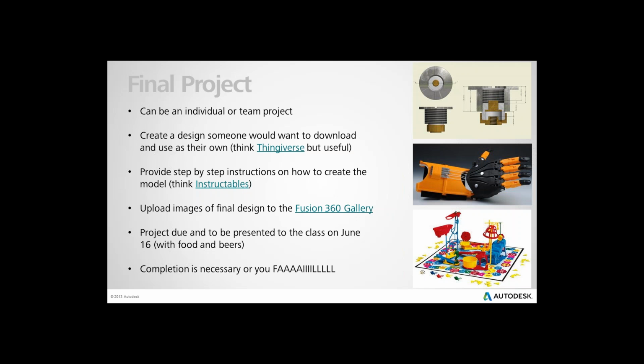You don't scale stuff. Parametric is exactly that. This is a parameter to the function. It will behave exactly in the way you describe this function. This is a model. It's not just, scale everything by 2. You set up the different values for different sizes. You have table lookups and parametric configuration. I don't think so. There are scripts, but it's all automatic. You put in the parameters of that part and that's the way it is. I'll ask you offline. I think there's a gap in the logic in that one, but I'll ask you offline. Okay.